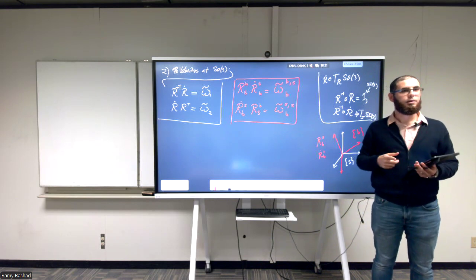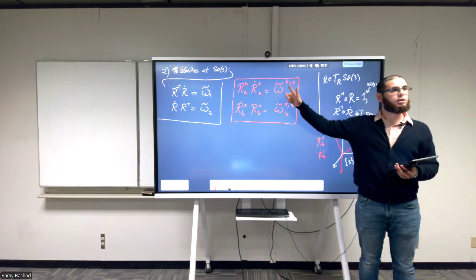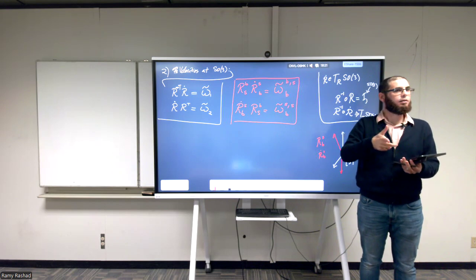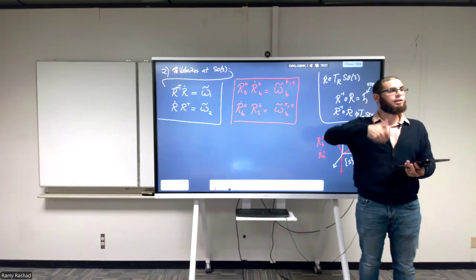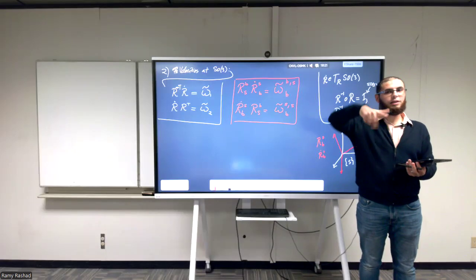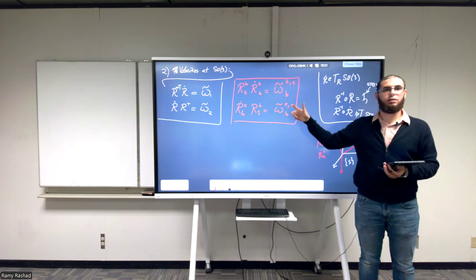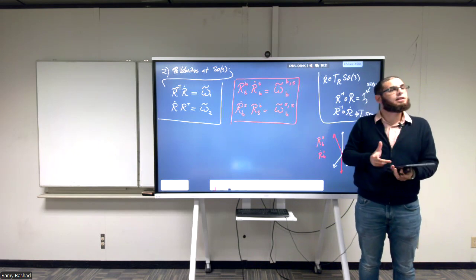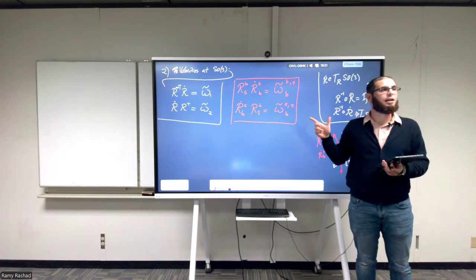The body frame. A gyroscope always measures the angular velocity with respect to some fixed frame that you have. You usually calibrate it. And then you represent this number into the body frame that you're rotating with. Okay? So the gyroscope measures this quantity. If you want to get this quantity, you need to measure it from something that's fixed, not something that's rotating. So you need to look at the body that's moving from something that's fixed.